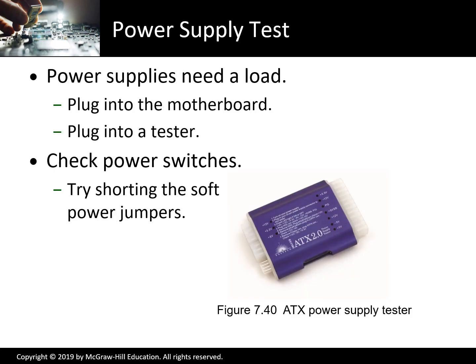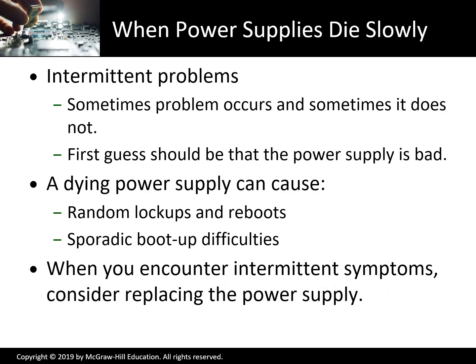Now, you can buy a power supply tester. It's cool. You just pull the cables off the motherboard, stick them in the tester, and it will tell you which ones are working, which ones aren't, and even give you the voltage. Now, sometimes problems occur, and sometimes they don't. Probably want to look at the power supply first. If it's random lockups and reboots, it could be a power supply problem.